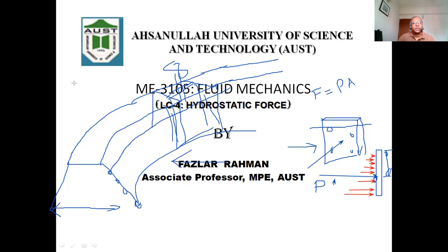So this plate, if you think of it another way, is like a beam with this pressure working on it. Let me take the arrow right over here, and you have support at both sides. So this is the support. Then if you know this force and its location, then from the geometry and the location of this pressure, you can figure out these two reaction forces, this one and this one. Then you can design the sluice gate.